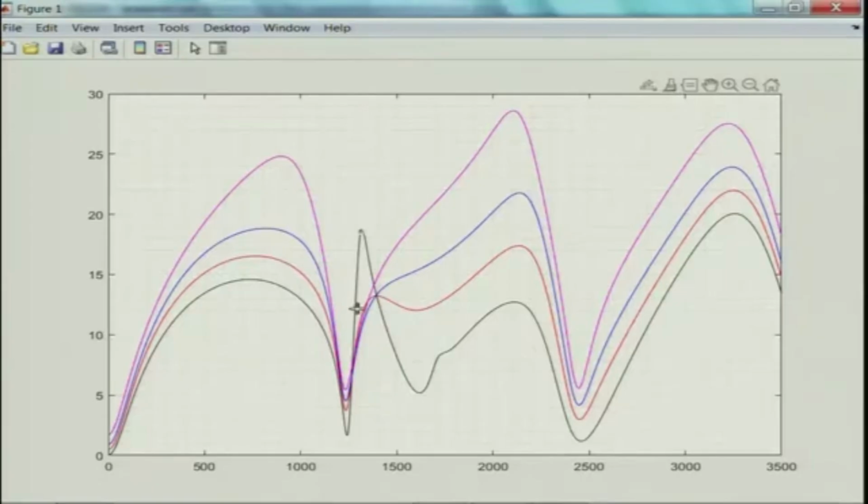But nevertheless, one thing is clear using the modern expressions where mean flow, mean bias flow and mean grazing flow occur simultaneously, and these expressions can readily take care of that. We will also use the previous expressions known before and see how the shape of the curve changes. What we however notice is that mean flow definitely tends to increase these domes, at least for the cross flow expansion chambers, and black one was for zero flow.